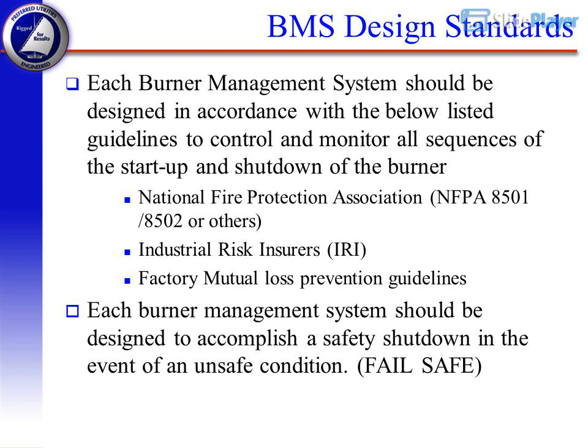BMS Design Standards. Each burner management system should be designed in accordance with the below-listed guidelines to control and monitor all sequences of the startup and shutdown of the burner. National Fire Protection Association, NFPA 8501/8502 or others. Industrial Risk Insurers, IRI. Factory Mutual Loss Prevention Guidelines. Each burner management system should be designed to accomplish a safety shutdown in the event of an unsafe condition.